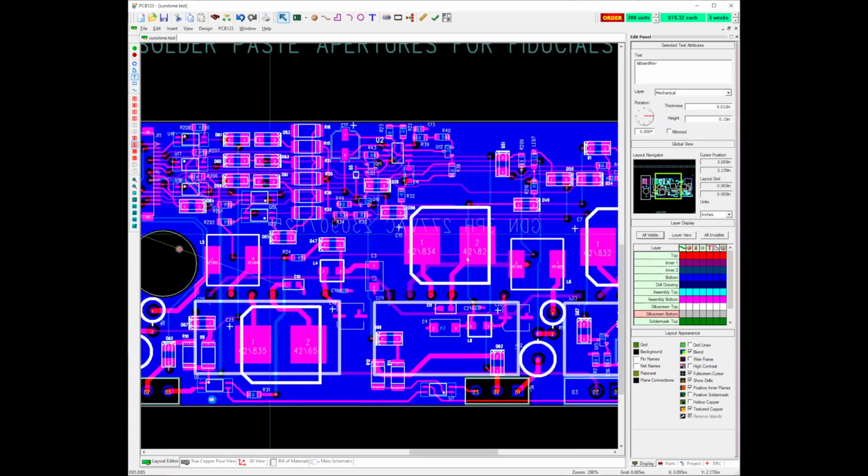Design changes. Let's say you've got a completed design and you want to make a change to it. I want to change a capacitor. Well, a couple things happen when you change a part. If you just delete a schematic symbol and put another one on, and then you come back to your board, your routing's all gone.